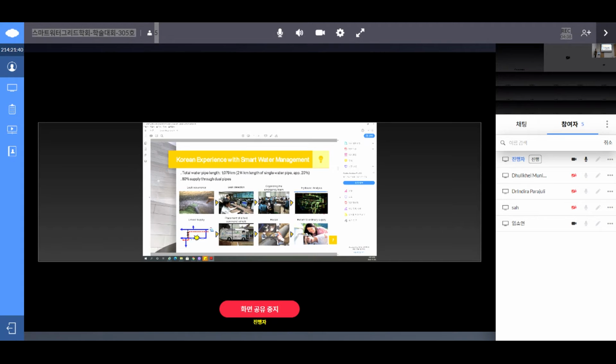This is the 8-step process in case of a leak. First, the leak is detected through sensors which send signals in real time. Then an emergency team is organized. A hydraulic analysis of the model is performed, because the model is represented in hydraulic modeling software in real time. A linked supply is put together. As you can see, there is always more than one route to provide water. So if one pipe is in a situation of failure, then you can provide water through another pipe. Then they deploy a field command vehicle, repair the break, and go back to ordinary supply.